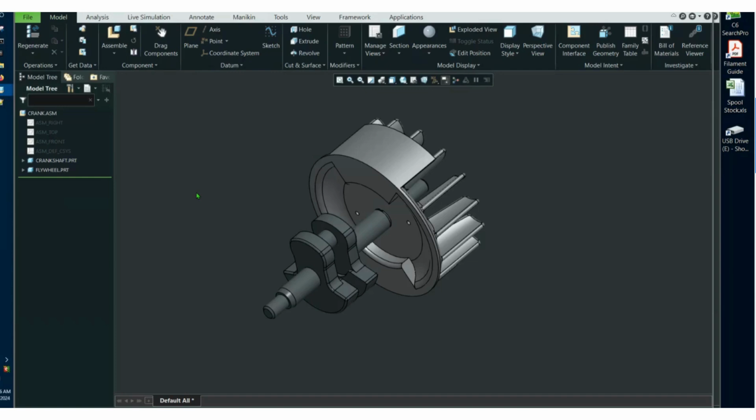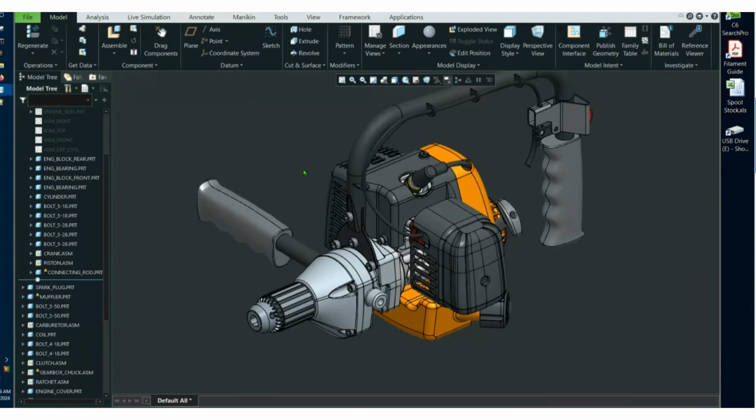And this is why, when we start with a failing assembly that we open up and there's a whole bunch of crap that's all blown up and it's scatter shot, if you see missing components, go there first. Get the missing component issues resolved and see if that doesn't build out the rest of the assembly, like we've seen in this case. That's a good place to start. It's not guaranteed that they'll solve all the failures of a blown up assembly that you happen to be the unfortunate recipient of, but it's definitely the place that I recommend everybody start, because as we see here, this is a really good example. Everything that was wrong was because that component was missing.